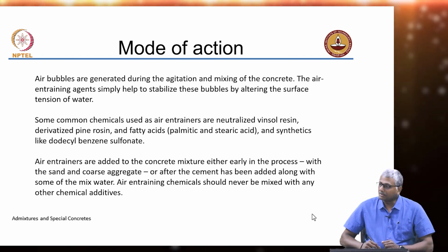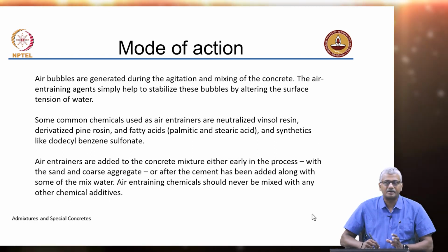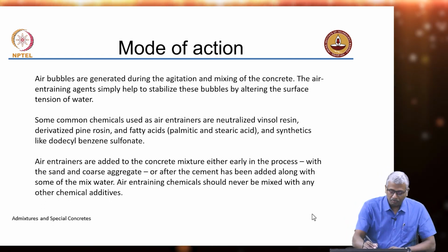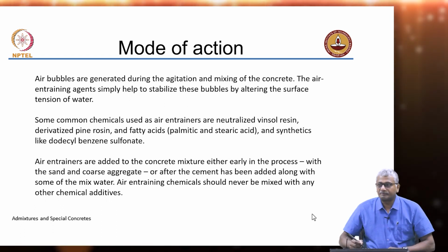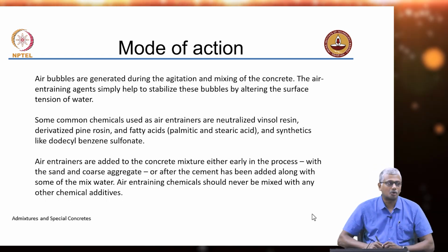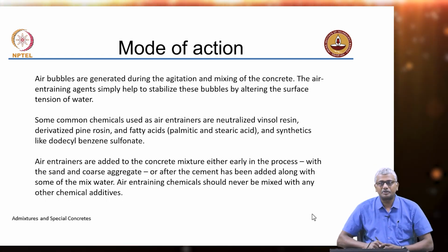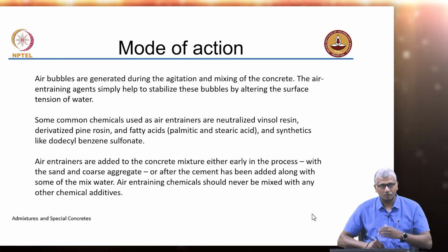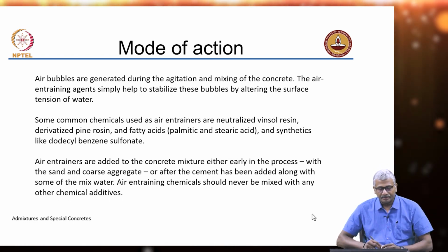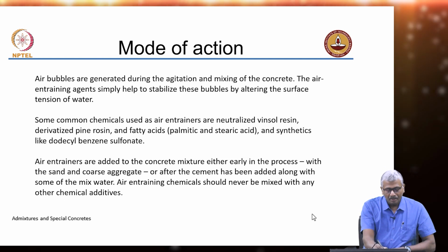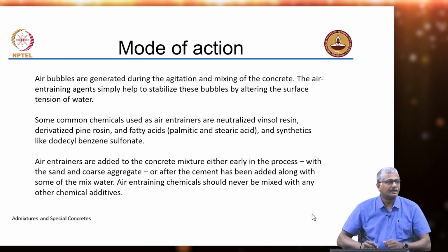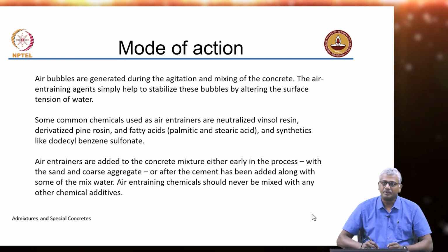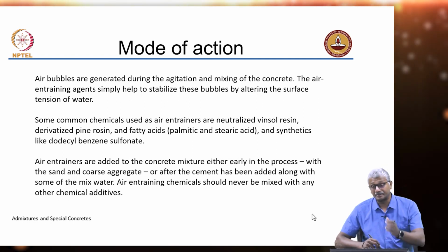Now, where are these alkalis coming from? Mostly, these alkalis are present in the raw material in the form of alkali sulfates. Alkali sulfates are usually present as impurities in the raw materials, and these basically come into the compound mixture that we have. So, the sulfates that are indicated here are not just from the gypsum that we add in the final stages, but also could be from the alkali sulfate sources that are available as impurities in the raw materials.